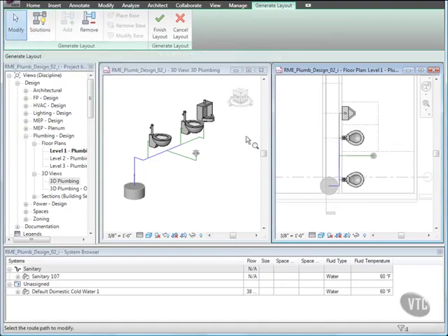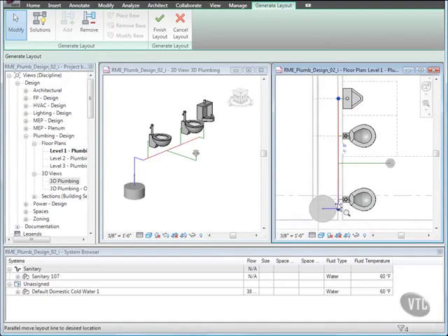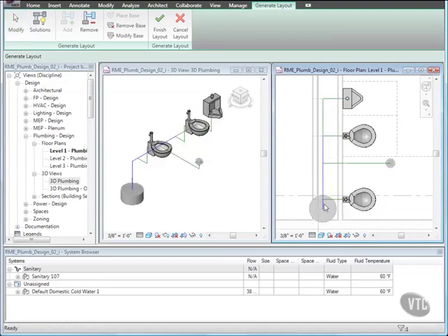Next, we'll customize the suggested layout. While pressing Ctrl, select the vertical route path segments. Then, click and drag the parallel move control, the 4-way arrow, to the left and align all 4 segments to the base point. Then, in the 3D view, use the view cube to orient the view as shown.